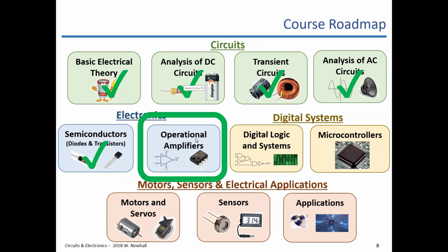Okay, so op amps are, I think, really useful devices. If you have to amplify a voltage, make a voltage bigger, like multiply it by 10, let's say. Suppose it's a sensor signal, an audio signal, something like that, that you have to amplify maybe to get into a data acquisition device from a low voltage sensor. Operational amplifiers are a great way to go. So maybe you have a temperature sensor, its voltage range is maybe only on the order of millivolts, and you need the span to be like 5 volts for a data acquisition device. This is a great way to do that.